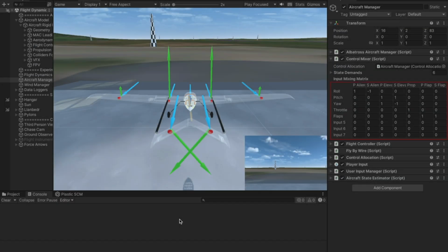The proper inputs from the pilot should result in the correct matching outputs by the control surfaces, according to a static control response test that followed. This test revealed that the elevator, aileron, and rudder controls of the aircraft needed adjustments, either from -1 to 1 or vice versa, and the port flap needed to be engaged by setting the value from 0 to 1.